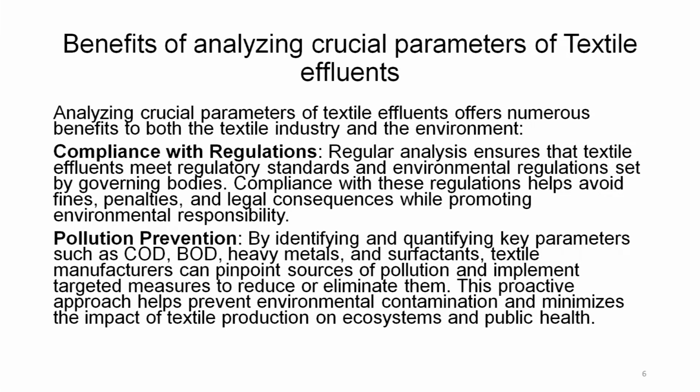Pollution prevention. By identifying and quantifying key parameters such as COD, BOD, heavy metals and surfactants, textile manufacturers can pinpoint sources of pollution and implement targeted measures to reduce or eliminate them.